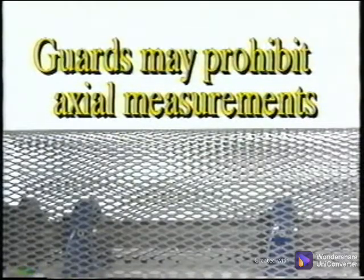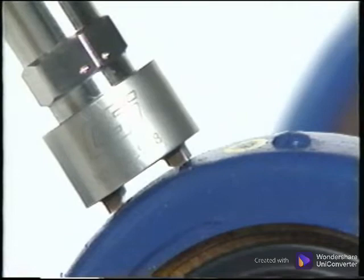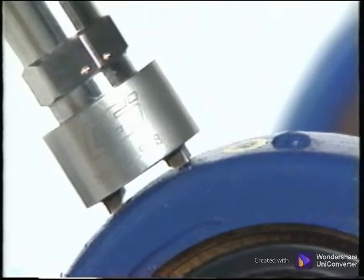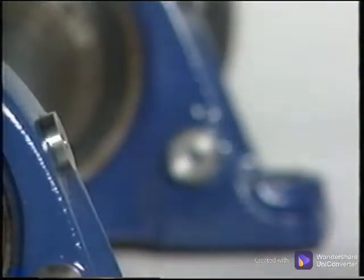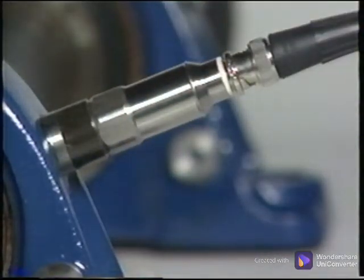often prevent that. A better way to measure the covered pillow block bearings is to install a hatch door so that a magnet mount sensor can be used. The linear frequency range will be increased substantially to be sure to catch bearing degradation. Oftentimes, the pillow block bearing has rounded surfaces that cause the magnet-mounted sensors to rock. In cases like this, it is better to install a mounting pad for the sensor.